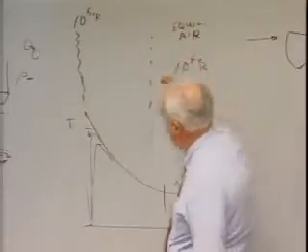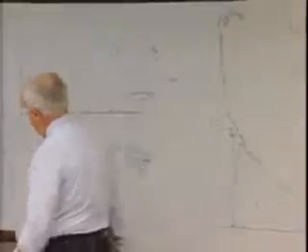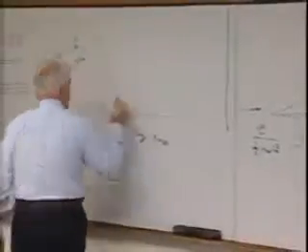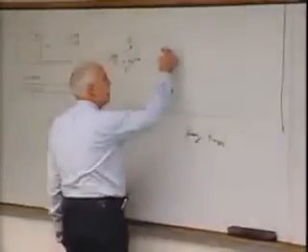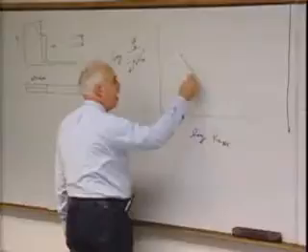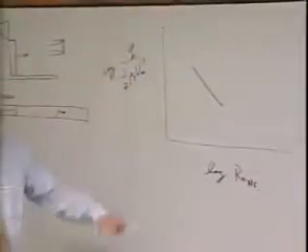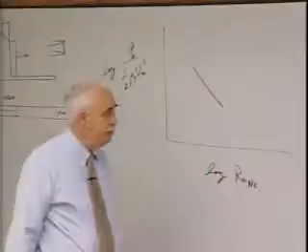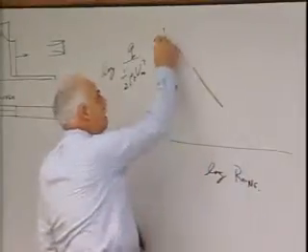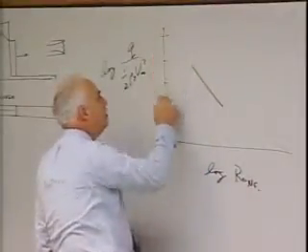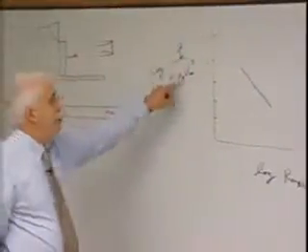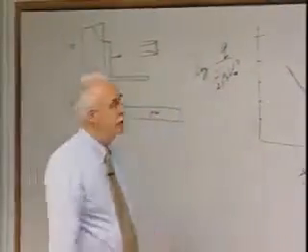Okay. If I look at either wind tunnel data or flight data, in the region of prime concern, I've got that -1/2 slope from that square root Reynolds number. I also have a bound up here that my heat transfer cannot exceed the energy flux.